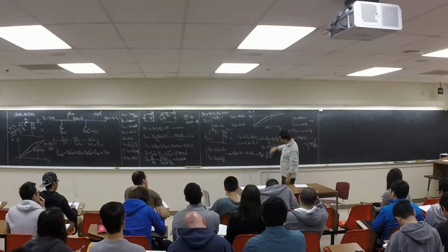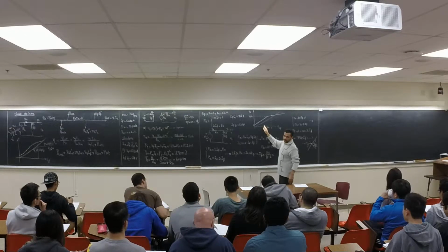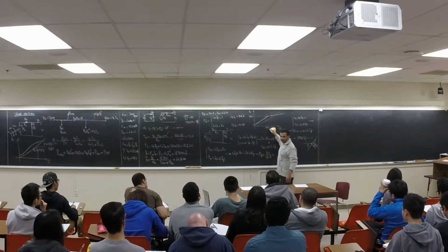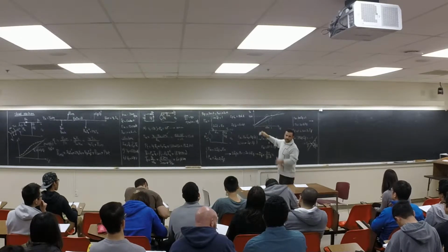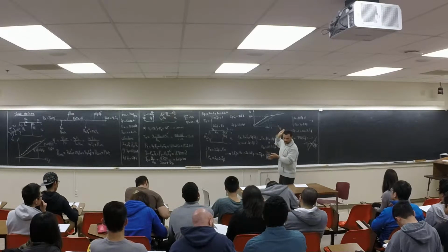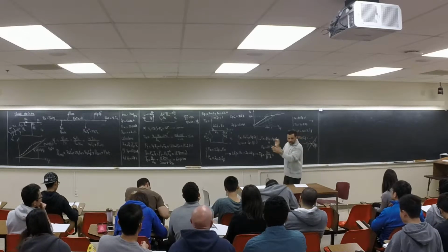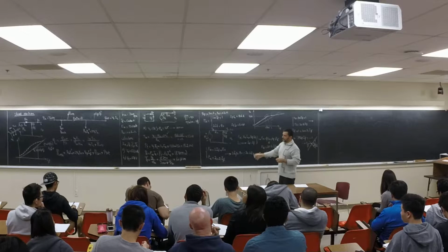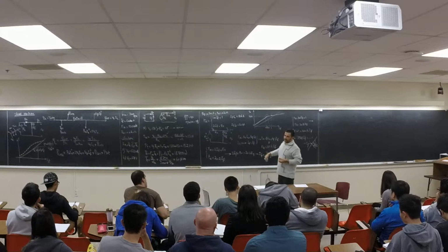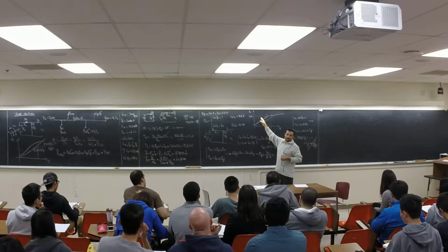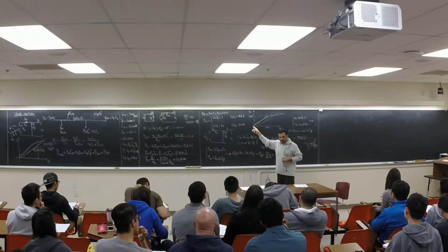See, if I solve this equation, the number comes to 0.7. Is it correct or not? No. The current cannot be less than this, right? Because we said it's going to cross here, right? If I come up with something like 0.7 again, one of them has to work. You know what I'm saying? You select this one, you end up with a negative current. You select this one, you end up with the right current. So good. But let's say we started with this one. First time we didn't know which one to start with. We started with this one. The current came out positive, but for example 0.5. That's wrong, right? Because this equation is not valid for 0.5, right?